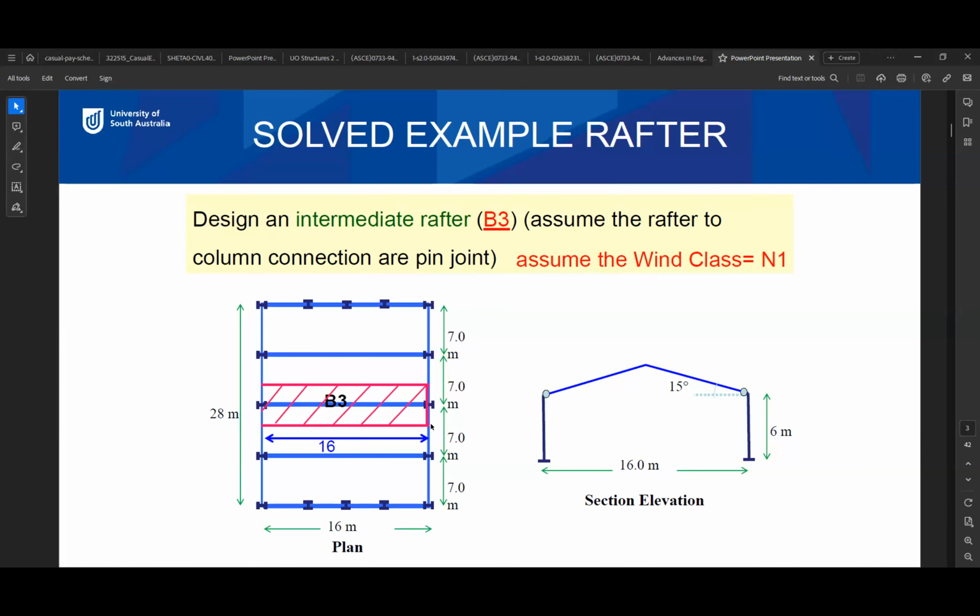Are you asking that question? Yeah, because from here, this is the important thing when calculating the load on a beam or column: what is the load width carried by this beam. So the load width of B3 is half the bay from top, half the bay from bottom. So it is almost 1 bay, exactly 1 bay, which is how much? 7 meter.